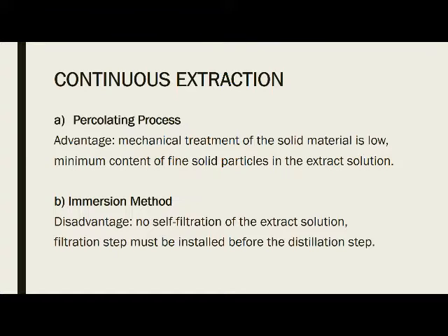And the last one is the immersion method. For this process, the solid material dips completely into the solvent and is mixed with it. Therefore, no special percolation properties of the solid material are necessary. But the disadvantage of this method is that no self-filtration of the extract solution takes place, and therefore, a filtration step must be installed before the distillation step.